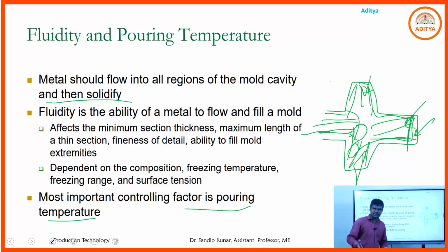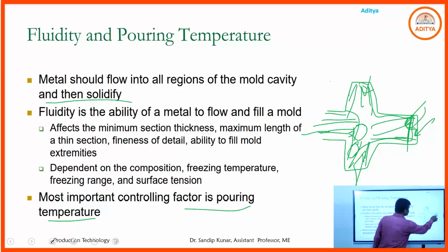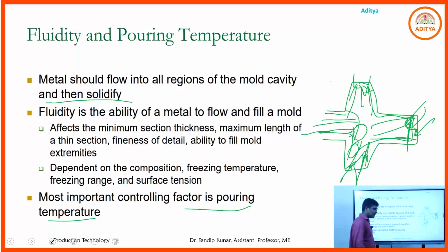So it is not a quality product. Maintain the pouring temperature and the molten material will flow to every section. That is fluidity and pouring temperature.